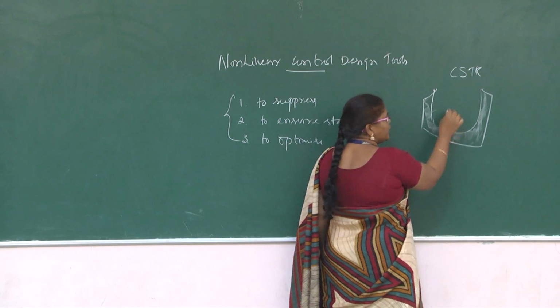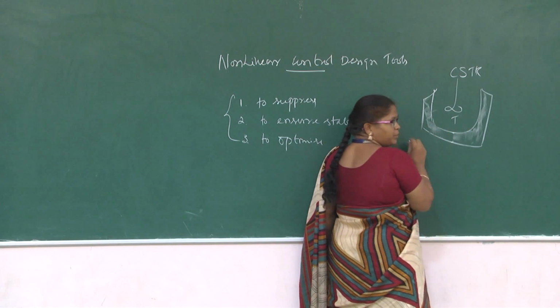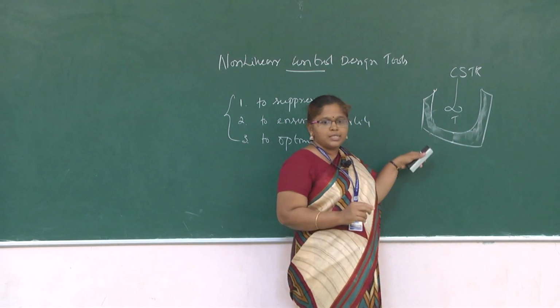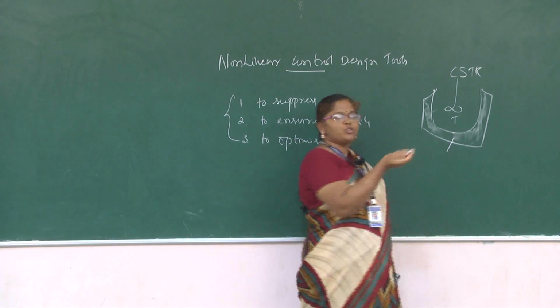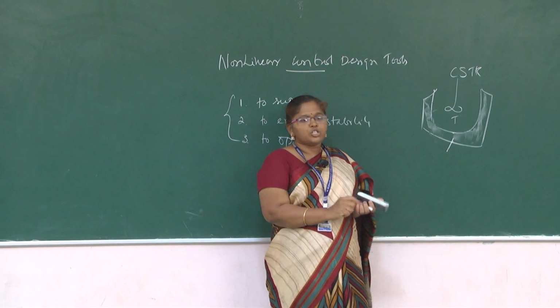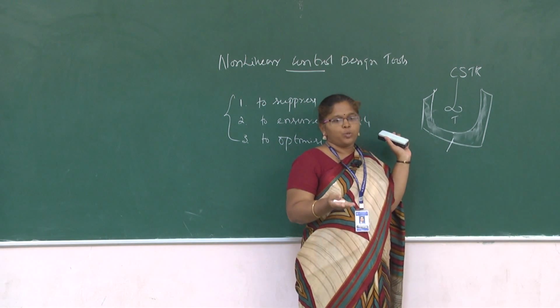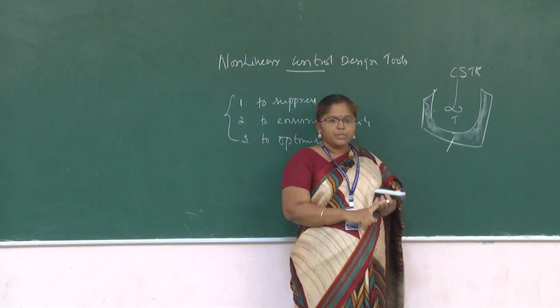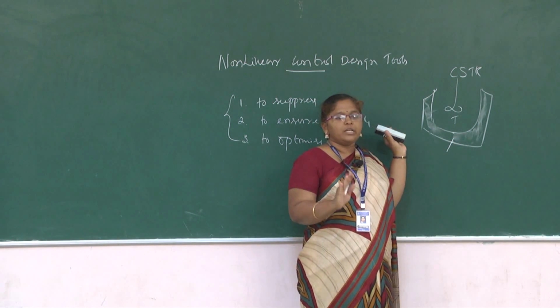Here we usually want to measure the temperature. This is the stirrer, we want to measure the temperature. Whenever we model this CSTR, we usually consider that the heat given to the surroundings is nil, but generally it is not nil. So this inaccuracy may cause some problem, but in linear control system, for simplicity purposes, we usually neglect this. So this is the problem in linear control system.